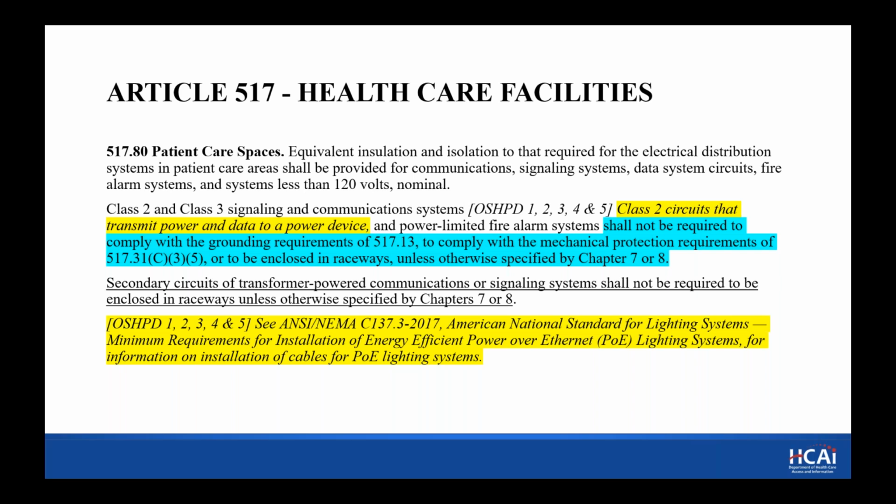Next question reads, what is the required accessible space for low voltage equipment? Code section 110.26. Well, if it has a 120 volt breaker, it would be that 3 foot clearance. So typically what we see is low voltage panels have a 120 volt source.